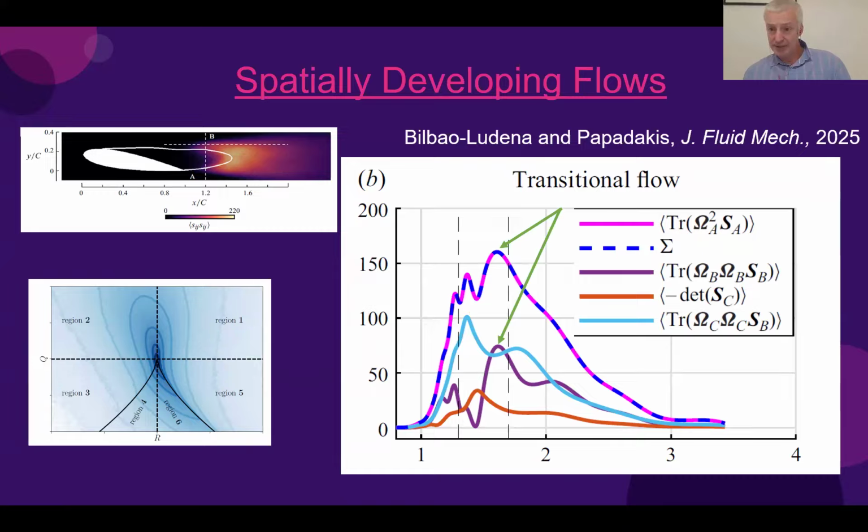So again, doing this decomposition gives you some physical insight into a result that isn't at all obvious to explain using conventional analyses. And so this perhaps suggests that there's some interesting displacement again between how entropy is being produced, because it seems to have an initial surge, then a gap, and then it comes back. And that gap is kind of infilled by this interaction from the shearing that's giving us this secondary peak. And this spatial separation in this production is clearly of physical significance. And it would be great if turbulence models could kind of capture this behavior implicitly.